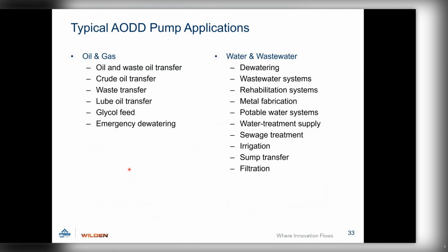Right, water and wastewater, we're huge in that industry. We have the largest pump in the industry with a 4-inch diaphragm pump that's big in the water and wastewater industry. It uses a 5-inch ball valve with easy access to the balls. So if there's any kind of sludge or waste that gets stuck in there, they can easily take that lid off without pulling the pump out of service, and they can quickly dislodge whatever's stuck in the line and get that pump up and going again. Those are huge in sewer treatment facilities, for bilge pumps on ships and cargo tankers. They use those all over.